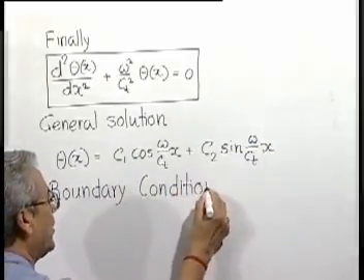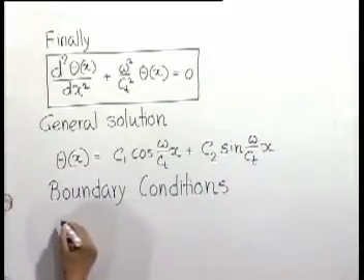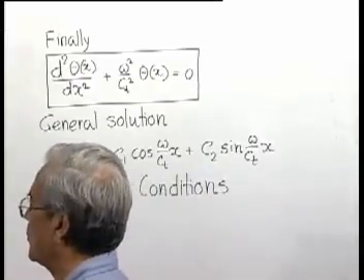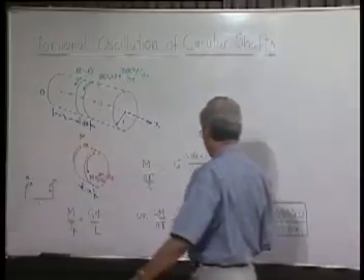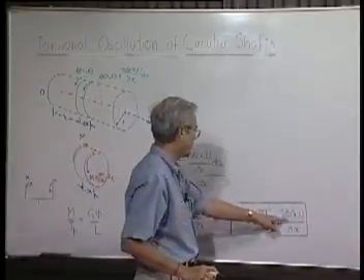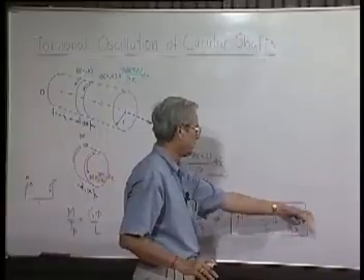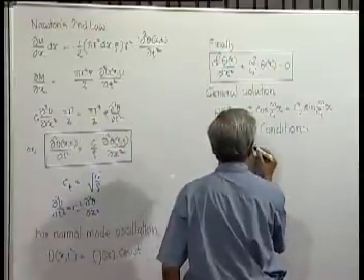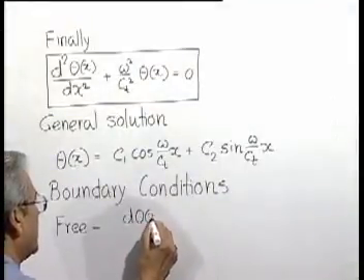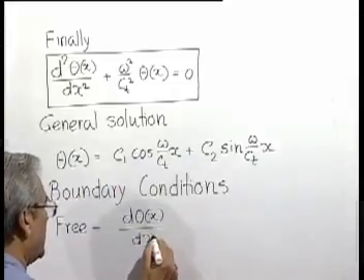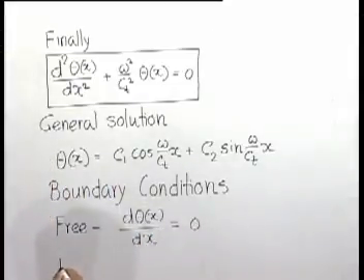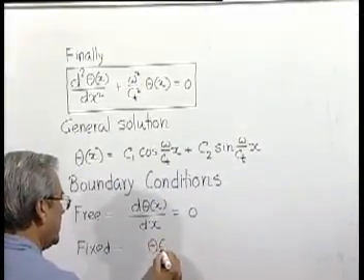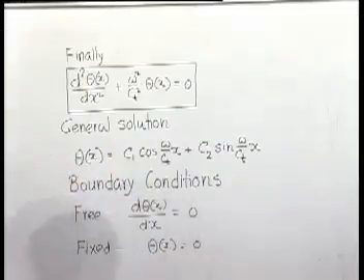boundary conditions can be of two types, that free means no torque or no moment acting there, and as we know, moment is proportional to theta dx, forget about the cosine omega t, and if that has to be 0 all the time, it means it is same as, and for fixed end, twist itself will be equal to 0 for all time.